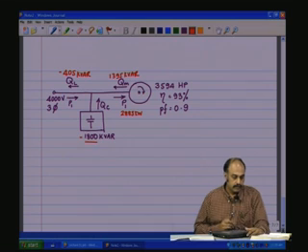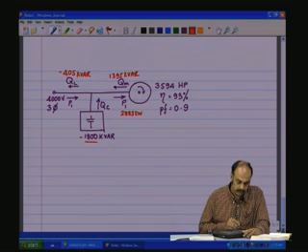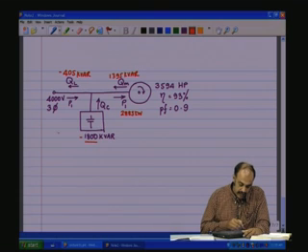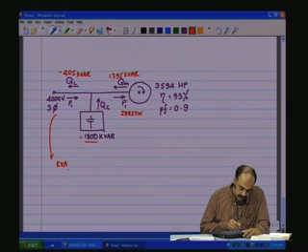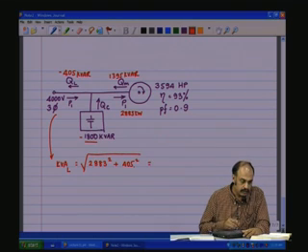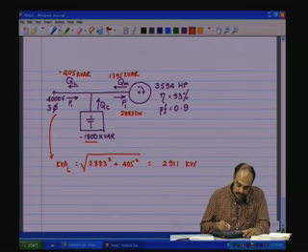Anyway, for this circuit now, we check the apparent power on this side. What is the apparent power? So, the kVA rating line side is root of 2883 square plus 405 square, which is 2911 kVA.